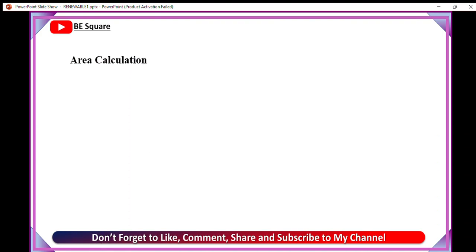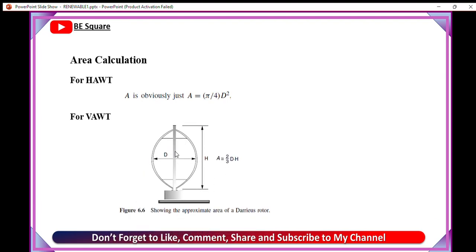Okay, what's the next point? There is area calculation. For horizontal axis wind turbine, we can calculate the area by using the formula pi by 4 D square. D is the diameter. For vertical axis wind turbine, area can be calculated by 2 by 3 D into H. D is the diameter and H is the height.